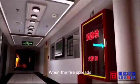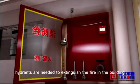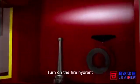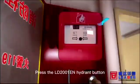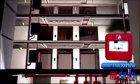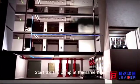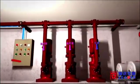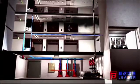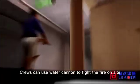When the fire spreads, hydrants are needed to extinguish the fire in the building. Hook up the water gun, deploy the hose, turn on the fire hydrant. Press the LD201 hydrant button. At this time, the hydrant button sends the alarm signal back to the central control room and starts the fire pump at the same time. Crews can use the water cannon to fight the fire on site.